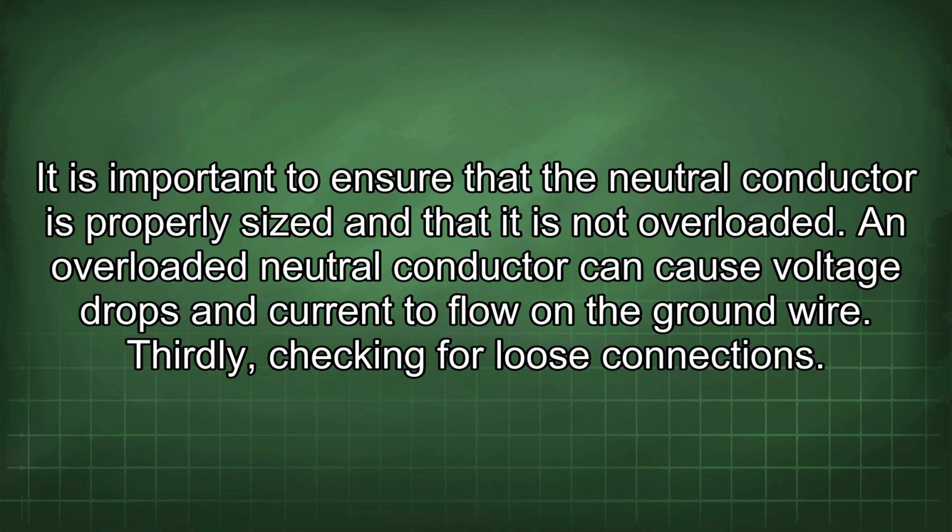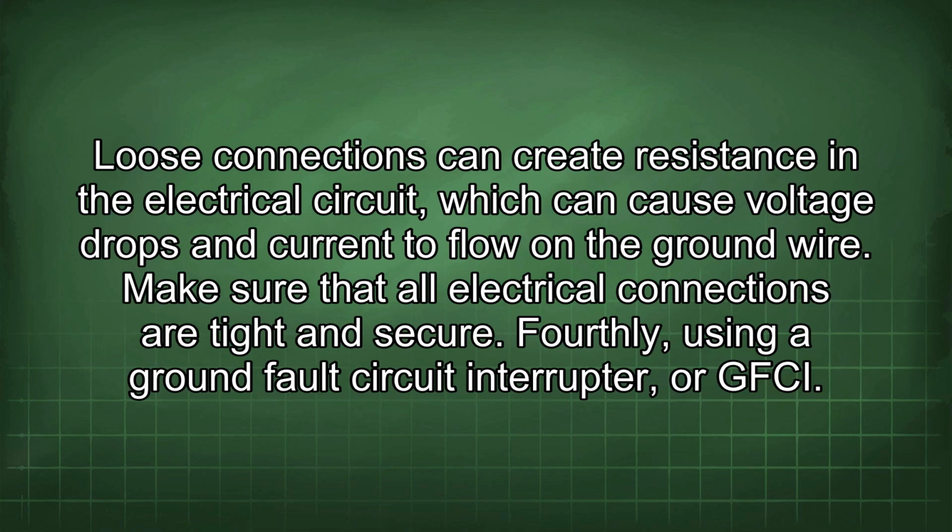Thirdly, checking for loose connections. Loose connections can create resistance in the electrical circuit, which can cause voltage drops and current to flow on the ground wire. Make sure that all electrical connections are tight and secure.